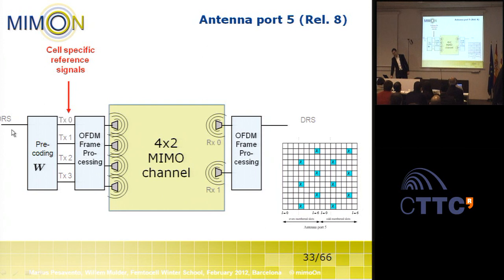These signals are transmitted before, or included before, the pre-coding. So before applying beamforming, the reference signals are included. In fact, we transmit these reference signals with a selected beamformer.